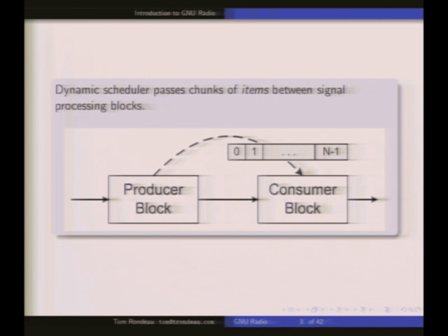And so what I mean when we move chunks of data, as I said, we're in that flow graph structure, so there's producers and there's consumers. So one block processes data in whatever way you want. Maybe it's just multiplying it by a scalar or doing a filter operation. So you're going to pull in data. He's going to produce a segment of data for the next guy to consume. So we're going to pass over some n number of items. And that's the n that we capped if we're trying to control latency.